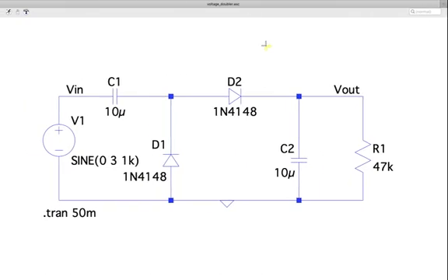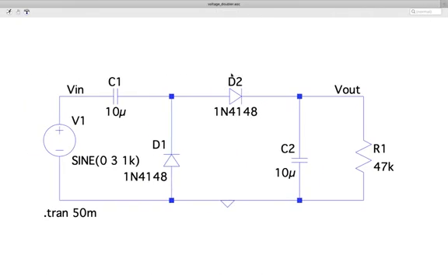But what happens is, because of the diode drop, like we know that diode drop is around 0.6, whenever this capacitor is getting charged, it is not charged to VM, it's charged to VM minus VD. Similarly, whenever this capacitor is being charged, it is supposed to charge to VM, but it also gets charged to a lesser voltage of VM minus VD.